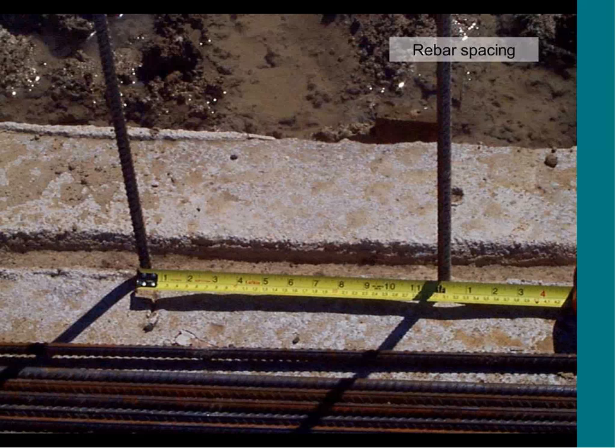Rebar spacing, that'll also be in your operation and maintenance plan. It should be what it's specified to be. If it's not, you want to make sure you stop someone on the concrete crew or the engineers out there to get that fixed. I was out at a site that had 12-inch spacing specified and we actually found 19. So that was fixed by, I believe, the contractor, but if not, the owner said he was going to do it. And what they do is they can drill in and set bar in between to make sure that they're meeting that minimum spacing.